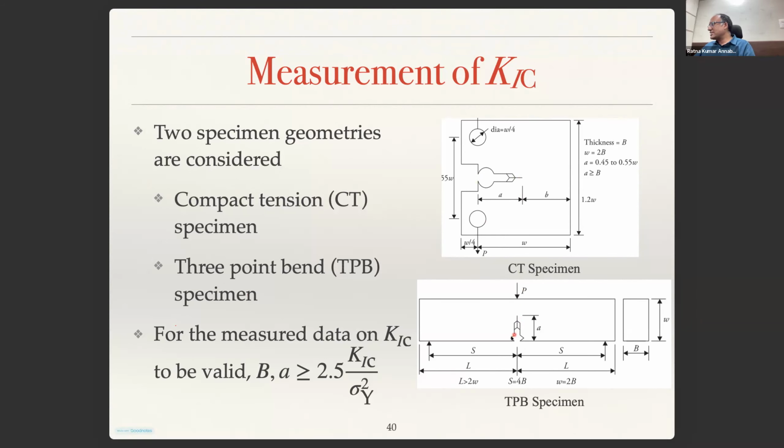Similarly, you have to do that. And you create such a geometry so that you can keep a strain gauge in this area, so that when the crack is deforming, when you're applying the load, these points will move apart, right? Then that deformation in that direction can be measured locally by putting a strain gauge in this region.